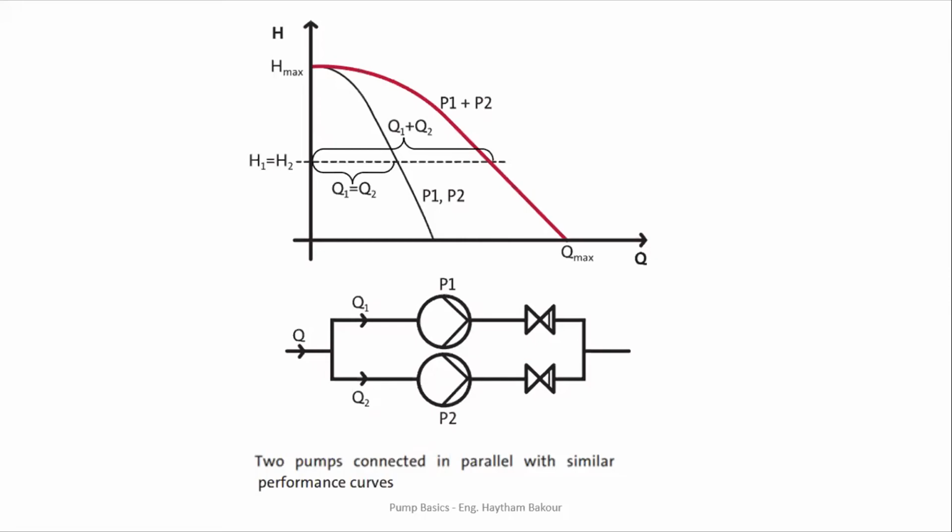So if we need to do any maintenance for one of them, we stop that pump and we start the other two pumps. There is no way, in practical and engineering life, to use one bigger pump without a backup pump for that. The best system is to have two pumps, each one covering half of the usage, and the third one as a backup, so we can switch between those three, starting two of them at a time and keeping the third as backup all the time.